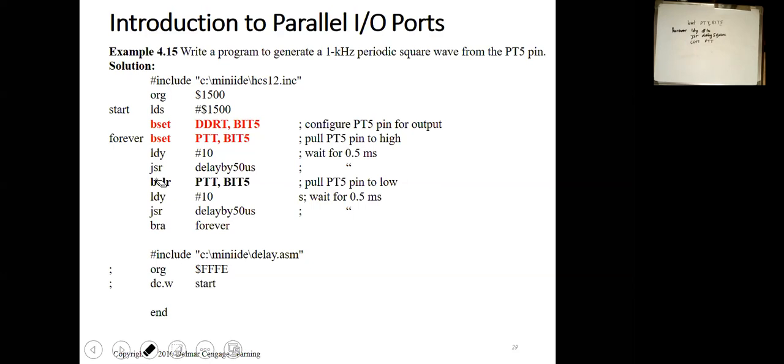So try after the lecture to complete this other version of the program. I think you need 2 instructions here in order to complement. Then you jump or branch forever. Basically, think about it, 2 instructions will do the job. A shift instruction, no, Muhammad, will not work. XOR is the choice.